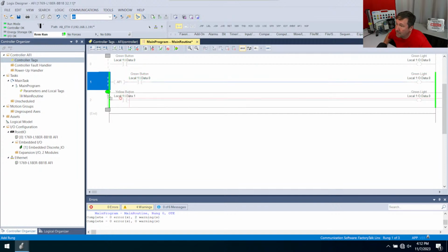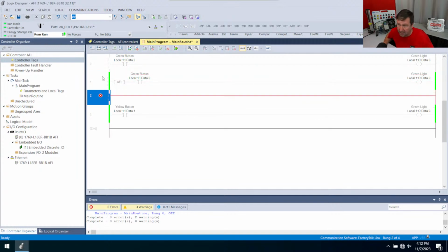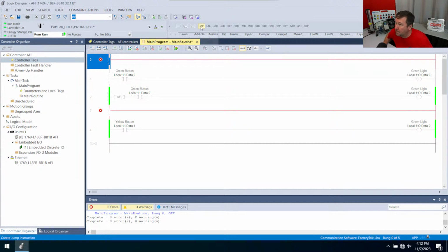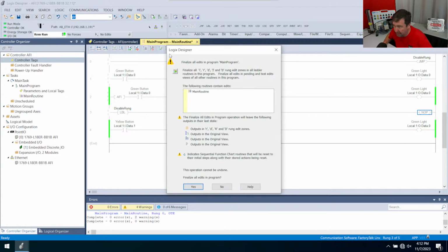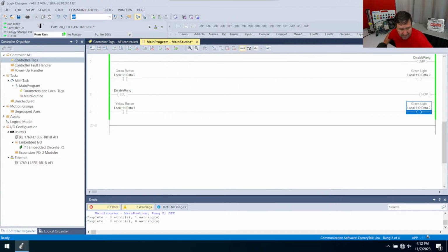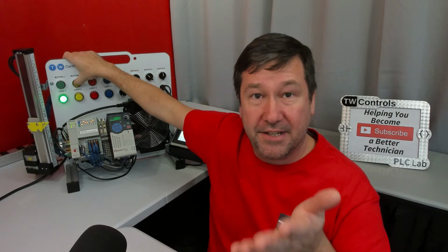So I'm gonna add a rung here, and we're just gonna copy and paste that one. There we go. And we could use a jump and a label, and we could do that. And I could just put disable rung. And disable rung. And then we could bring a no operation down. And we did a whole live stream on this, so I'm not going to go really deep into it. But that's going to solve that light flickering issue.